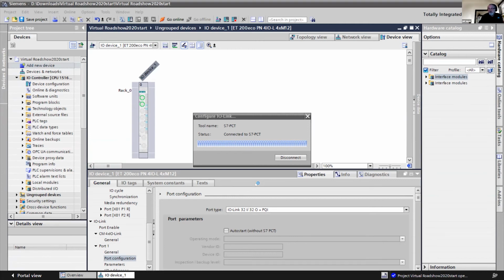But you'll see here now we have the SICK photo eyes and some registration sensors. We happen to be using this one today, which is an analog photo eye that has internally 8 different set points that we can configure. And I'm going to go ahead and grab that and drag it over into my IO-Link first port. We'll see here, this came from the IODD file, it gives us a description of the device and so forth.